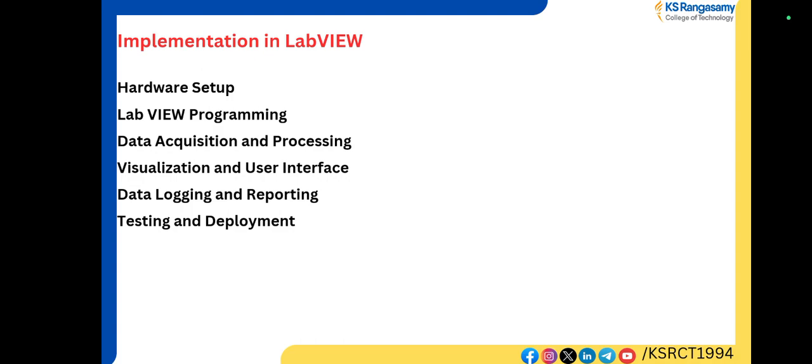Before performing any measurements, we have to perform the hardware setup. First we have to connect and configure the NI-DAQmx with LabVIEW using Measurement and Automation Explorer, and we have to install the necessary drivers for NI-DAQmx. The next one, after installing the hardware setup, is to create a project in LabVIEW. In it we have to develop a VI for data acquisition, signal processing and interfacing.